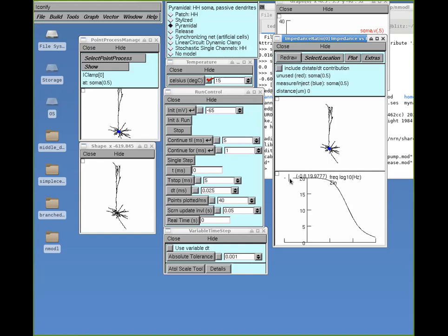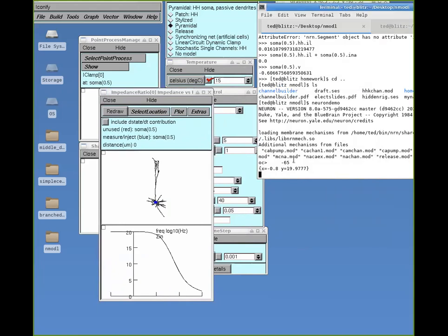I don't know if you can see that well there, but if I scroll across the top in crosshair mode and I click, I can see that the Y coordinate is pretty close to 20 megohms. And I can also see that if I drag this along, the input impedance starts to drop at around 3 to 5 hertz, maybe 7 hertz. And by the time we get to whatever is antilog of 1.8, what is that?